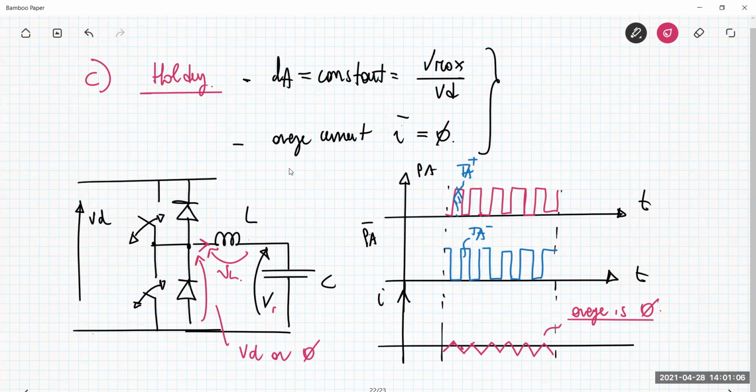Basically, this means that I'm in a situation in which I have to provide no energy, because if the average quantity is null, the average power provided from the switch power pole to the piezo actuator is null. The product of the voltage and the current is null. I'm dissipating a lot of power, which is the switching power of the two transistors that are switching on and off. So this is a typical nonsense. I'd like to provide an average null power, but in doing this, I have to dissipate large dynamic switching power due to the switching action of the two transistors, leading to this behavior.